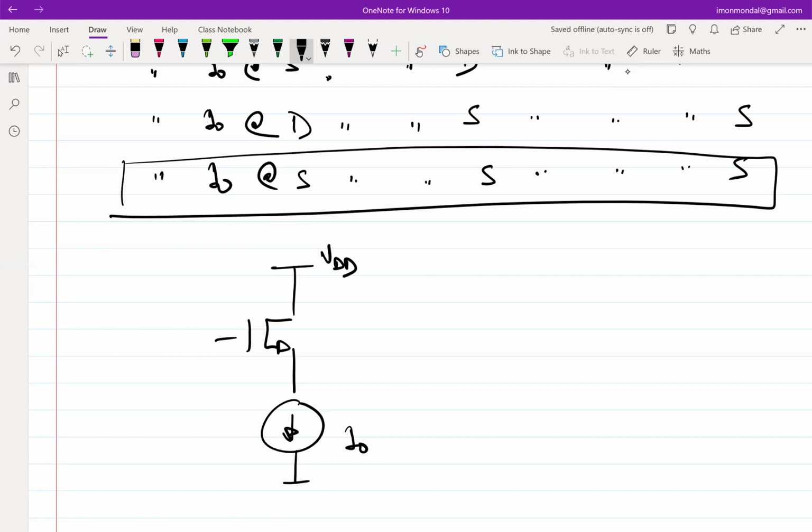So now the argument starts, right? The argument will be, we have to ensure that. By the way, if I just simply connect it like this, will it work? No, it's not going to work, right? So, okay, fine. We'll follow the same argument as we followed in the other case. So what was the argument? Let's assume that this transistor is pushing in some current, IDS. And like before, let's assume there is a small capacitor associated. It helps in visualizing the movement of voltage.